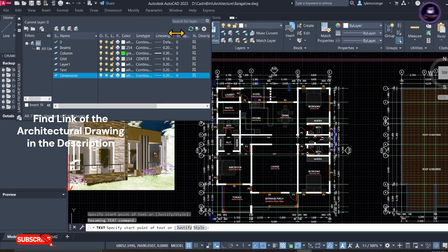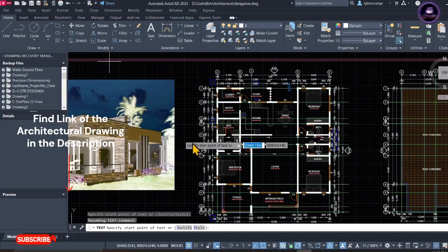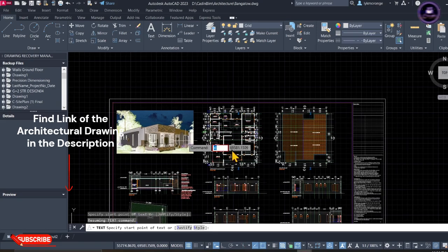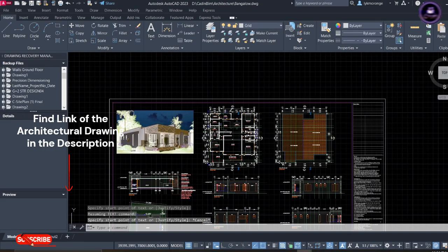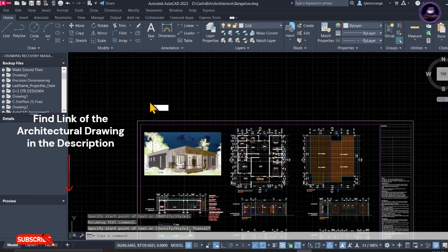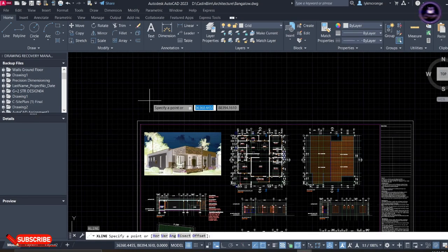So with this, just close. Once you close that, ensure that your layer here is in grid. Give it grid, and once you change it to grid, type XL, enter, for construction line. Just undo, and ensure that your layer is in grid, and then say XL, write it in caps, enter, and then you write the vertical, V, and you can see, yes, despite